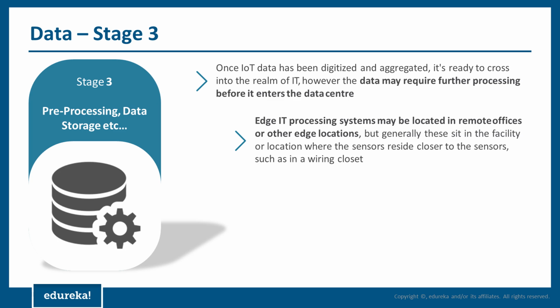If it is below 104, it discards the data or sends it to the next stage. Above 104, it immediately activates a stepper motor which will go ahead and trigger a shutdown of the boiler. Why? Because if the boiler shoots above 104 or 105, then it could be a disaster. So this is called edge analytics. So you did some analysis at the edge, correct?